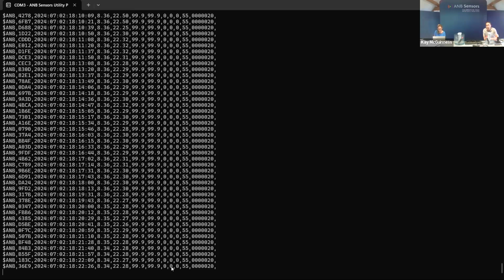The two zeros are around transducer and sensor diagnostics. We'll talk about those in a bit. That 0 there is basically a reserve byte. If we improve or include extra functionality to the sensor through firmware updates going forward, there will then be a number output in this one. The 55 is a nice reminder of the Modbus address of the sensor. And then the last number, the 20, is the file which all the data is currently being saved to.